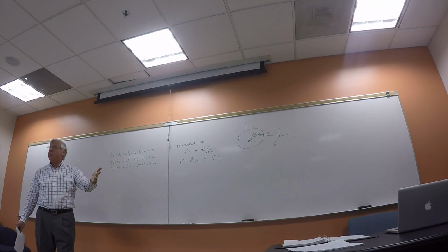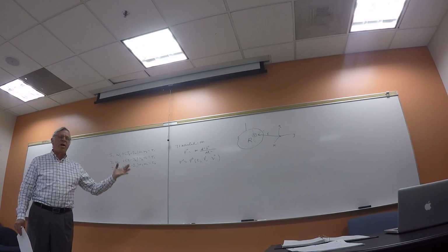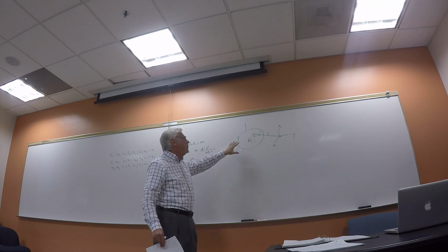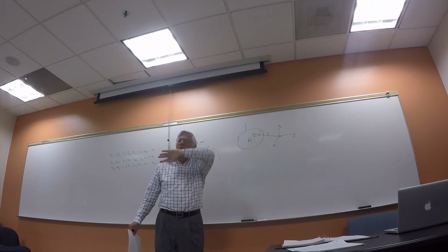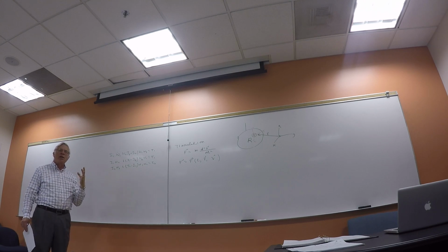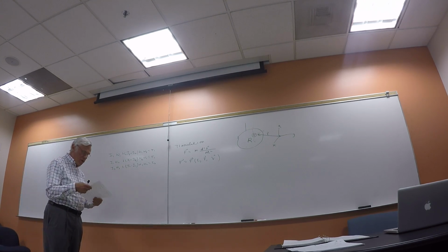When you have the product of dependent variables, it's always nonlinear, okay? So even something like a rigid body, and believe me, when you do spacecraft, you don't model as rigid body, you have to model as a flexible body, because of solar arrays and all types of stuff. But even the simplest concept of a single rigid body in space, when you look at the equations of motion, they are very difficult to solve analytically, okay? So that's another example of a nonlinear equation.